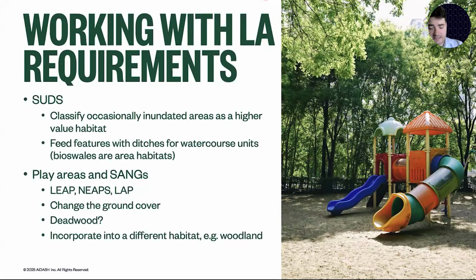How we feed that SUDS feature, our gut is to go for bioswales, and I think that's normally a good idea, but we can also go for ditches, because if we've lost watercourse units on site, then it might be valuable to use ditches to feed the watercourse, and then we can get our watercourse units back and things like that. So we can be creative in terms of how we fulfil these things. We don't need to necessarily just go, it's a SUDS, we put SUDS there.